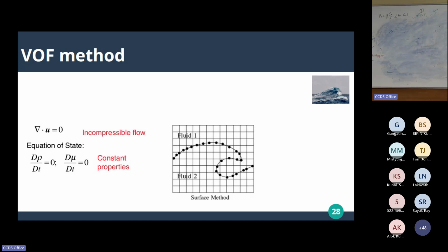So there will always be some kind of control, a field alpha, volume fraction field, shortly we'll learn. If it is one, treat it like liquid. If that alpha value is equal to 0, gaseous kind of thing. Based on that, I will activate. Oh, now you are in air, so use air properties.